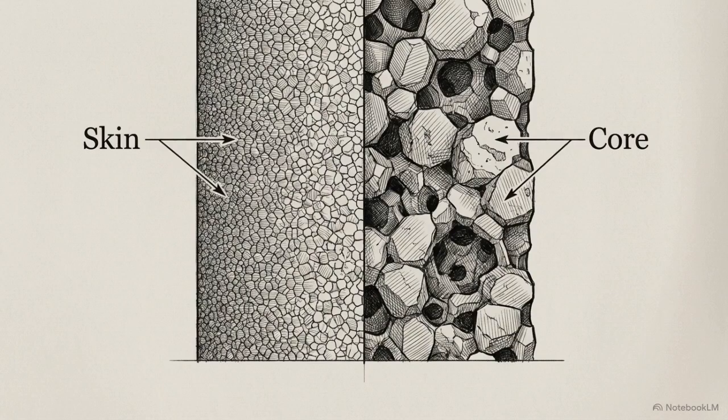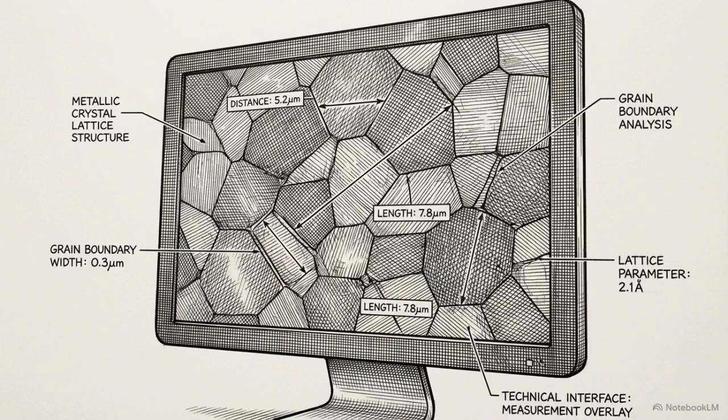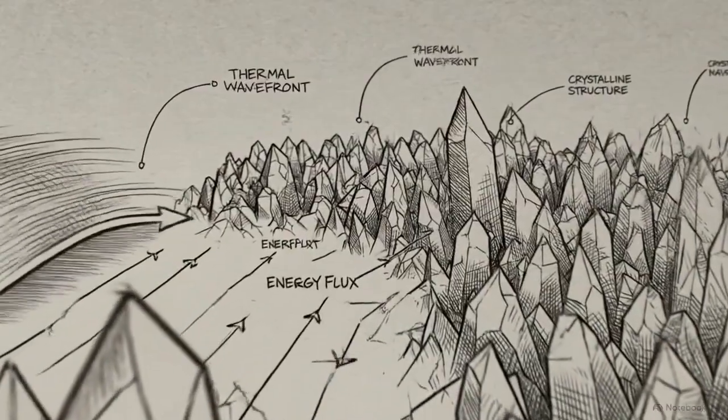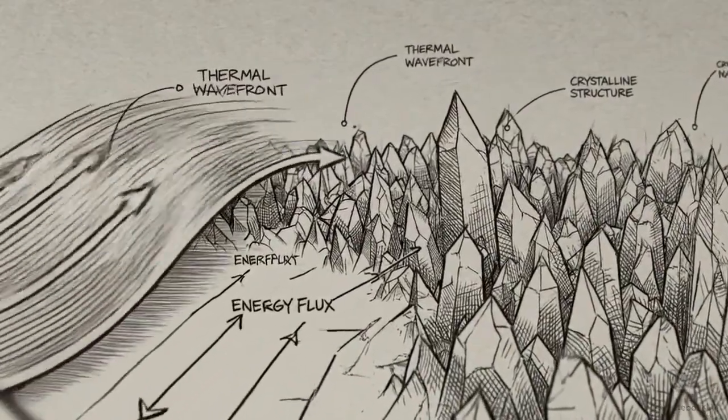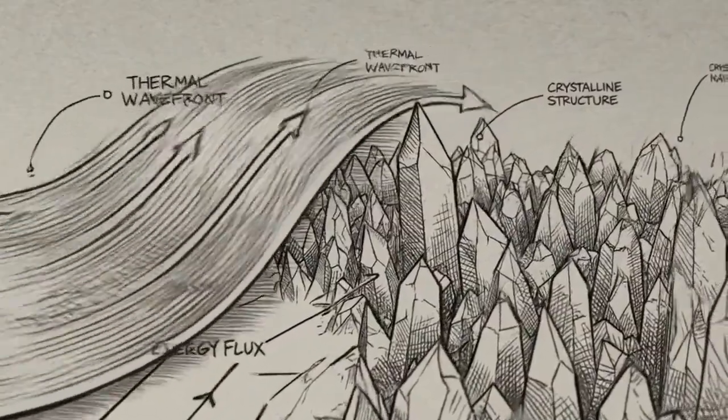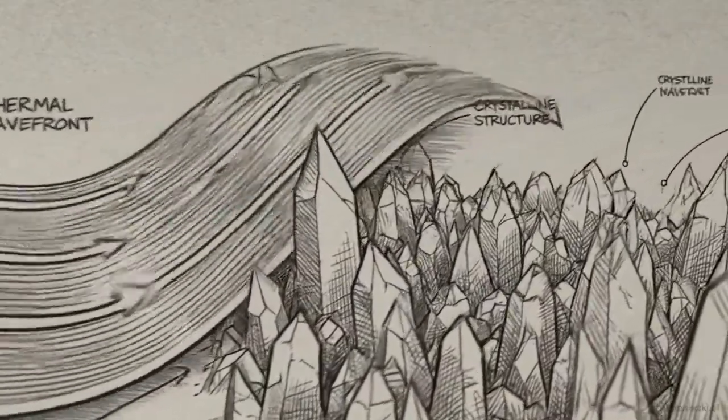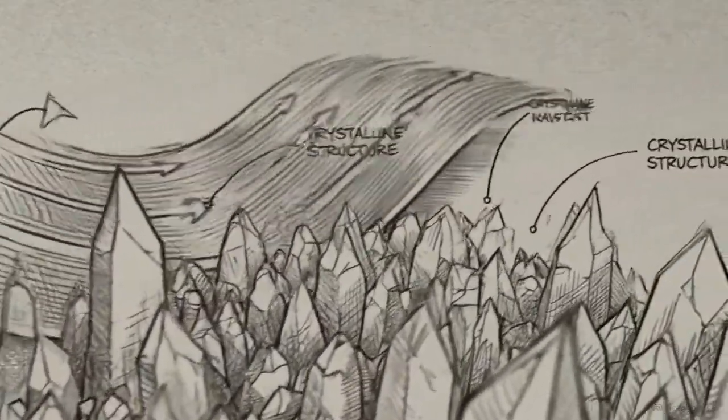The outer metal cools fastest, forming a dense, fine-grained skin, while the center cools slower, resulting in a coarser core structure. Controlling the quality of the final part requires engineers to precisely map and manipulate this exact distribution of microscopic phases. Mastering high-pressure die casting means treating the process as a rapid-fire chemical environment, where severe temperature gradients dictate the physical survival of the component.